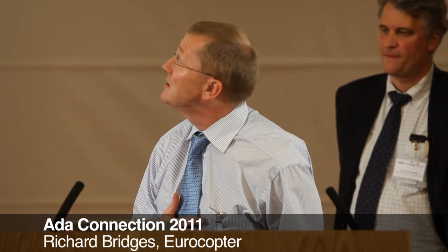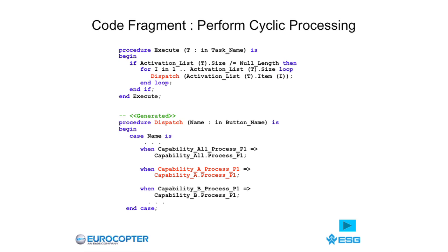Okay, so during runtime, in the operational running of the system, we have a simple dispatcher, which first of all, before entry at its allocated time, it just gets its activation list and then passes over this list, extracting the enumeration ID of the task that should run, and then dispatching that routine.